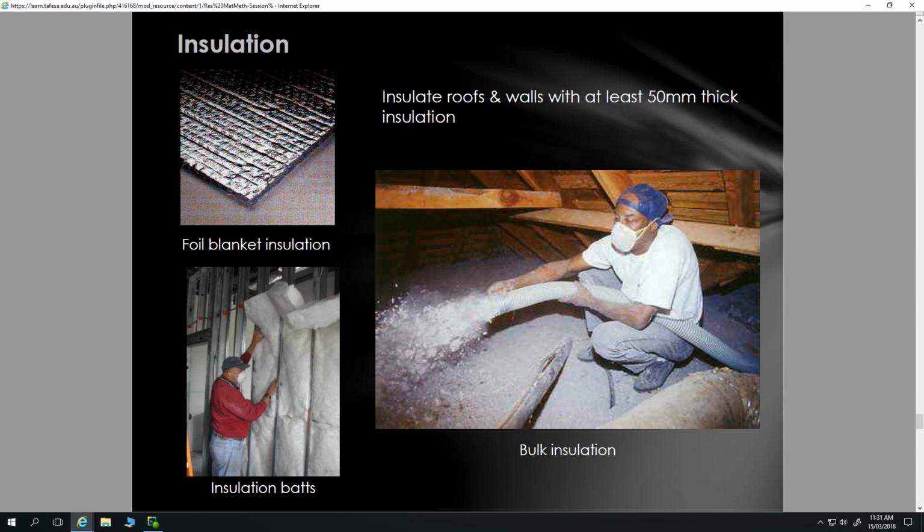But also I was looking at that for a raked ceiling, where to achieve an R value of 5, we're only dealing with 190 millimeters here, but we need at least 350 millimeters for our bats to achieve that R5. So we've got roof sheeting up here, or we've got purlins, roof sheeting. You know, our insulation bats would be coming down here. There's really just not the space for that.